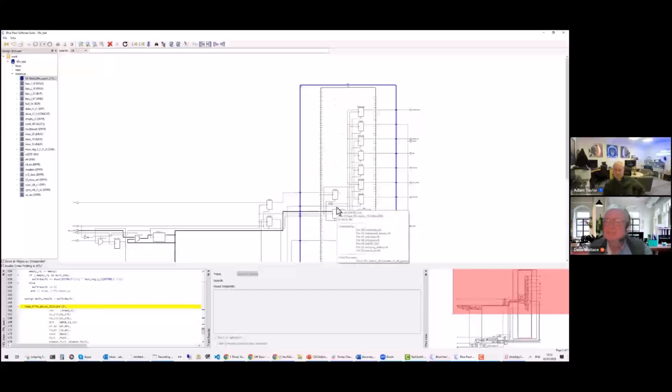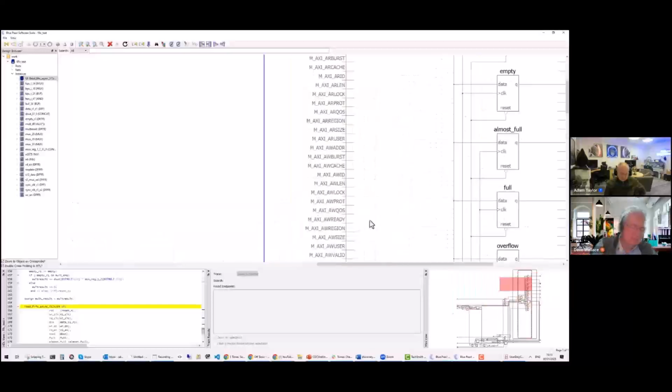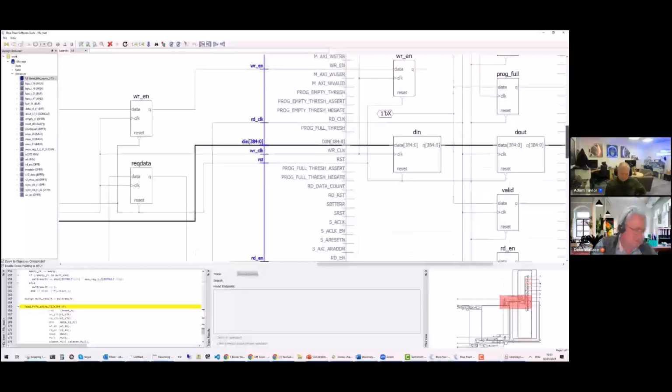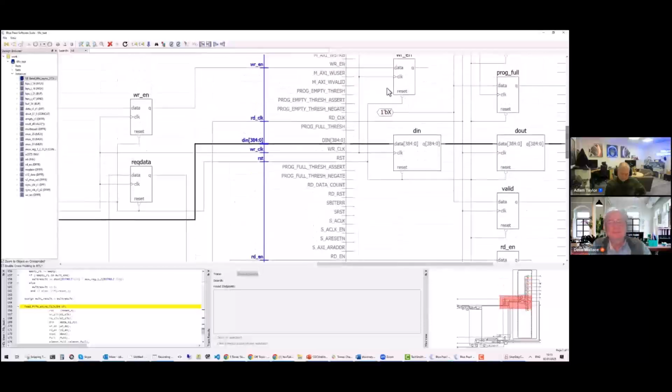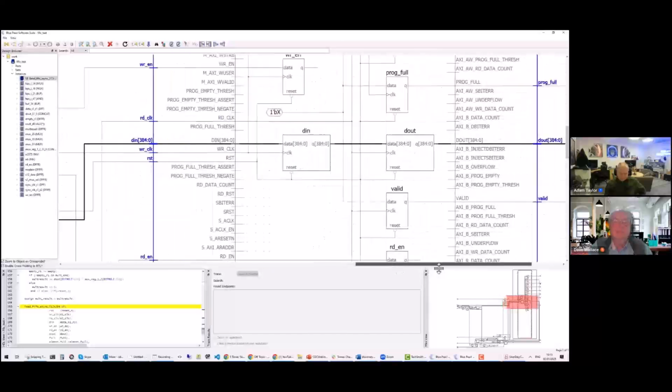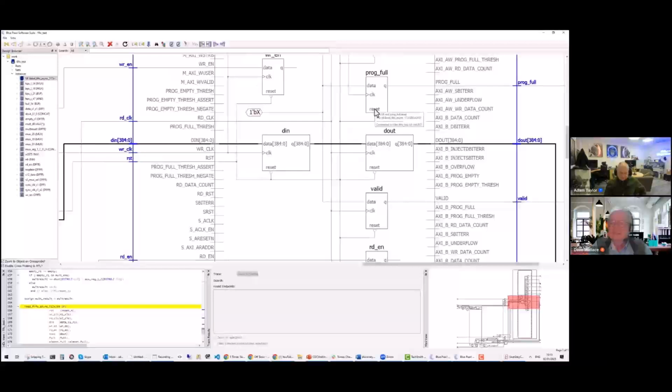Obviously, we want to be able to know what clocks the inputs are associated with and what clocks the outputs are associated with. So to help do the CDC analysis, when the model's been created in Synthesis, it has created this grey cell, and for all of the inputs, it's associated a FIFO. If we scroll down to that, we can see for the inputs, it's associated a FIFO with the relevant input signal and the relevant clock. And it's done the same for the output. So it's put a flip-flop in there for the relevant output signal and the clock.